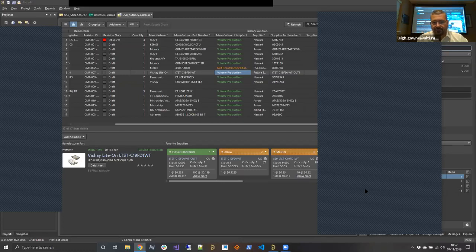At the moment, it is indeed possible to release a design and then share that with your manufacturer. The way that would work is your manufacturer would get an email link to a portal that they can navigate to and view various information on the project. So things like the vital statistics of the project, they'll be able to see previews, the 3D models. There's also a Gerber viewer in there to allow them to inspect the Gerbers. They'll be able to mark up and comment on those Gerbers, all of those things. And that exists in 365 today as well.